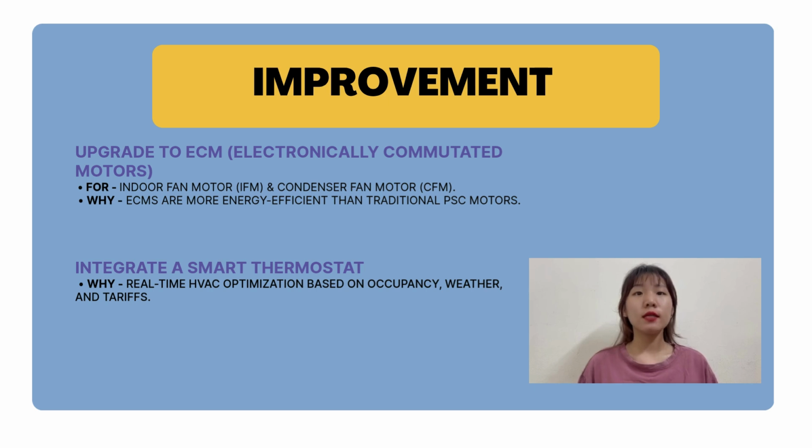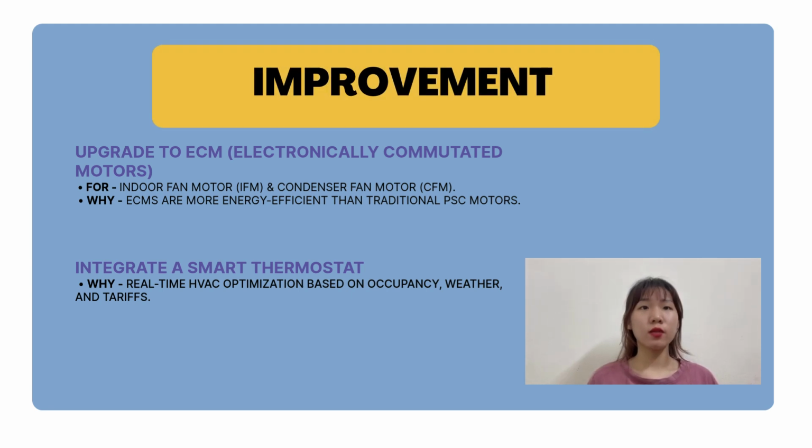Why ECMs? ECMs are up to 75% more energy efficient than PSC motors. Second, integrate a smart thermostat with demand response and scheduling. Next, we propose upgrading to a Wi-Fi enabled smart thermostat that includes scheduling and demand response capabilities. Why a smart thermostat? It optimizes runtimes using occupancy sensing, learning algorithms, and weather data.